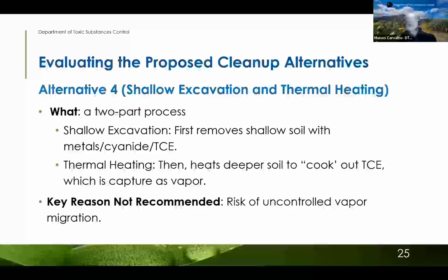The deeper soil would be heated, making the volatile organic compounds, particularly TCE, evaporate from the soil and groundwater. The vapor coming out from the soil and the groundwater would then be captured and treated at the surface. The process is fast, but the cost is the second highest.